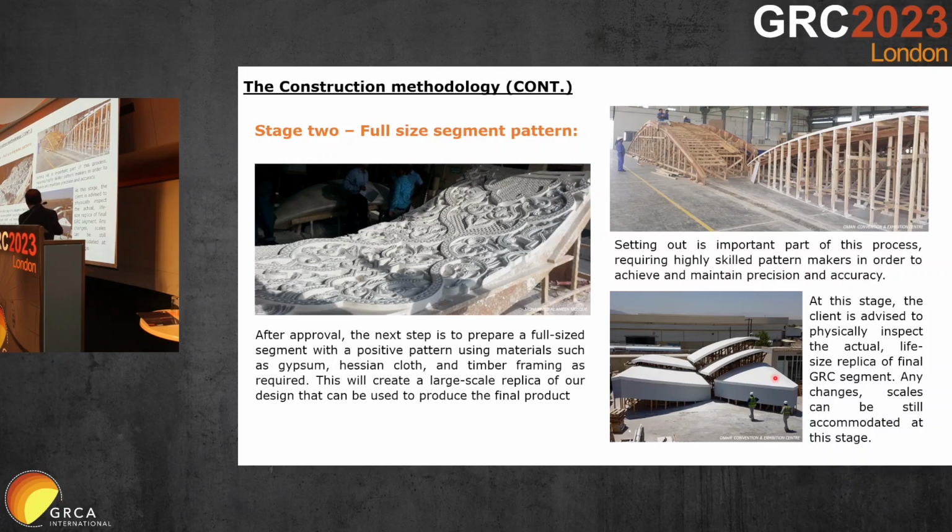Then this was again that 103 meter diameter convention center. This was a mock-up at 1:5 scale. You can see it with this human, and this is 1:5 scale. It is not full scale. So this was a mock-up of a petal at 1:5 scale, and there is steel inside, and on top of that GRC with those blue mosaic.